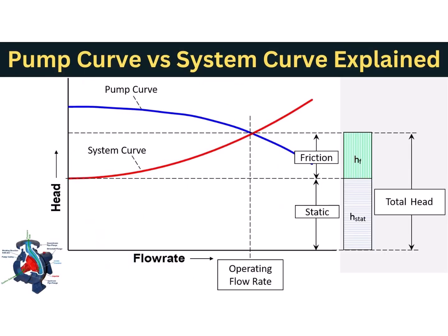And this is where we have your system curve, the existing system, the design system. It cuts the pump curve where they intersect.